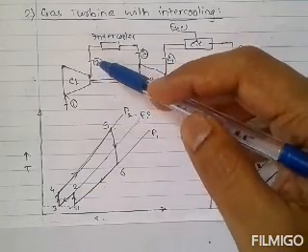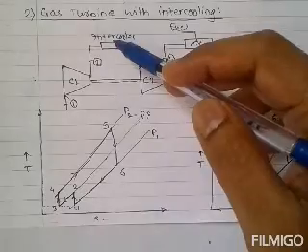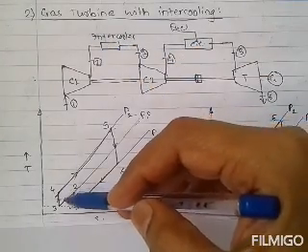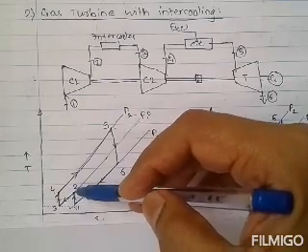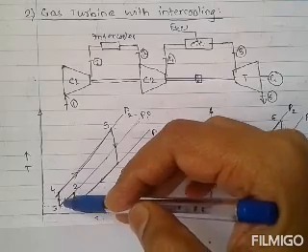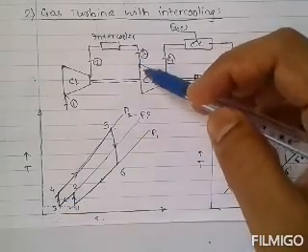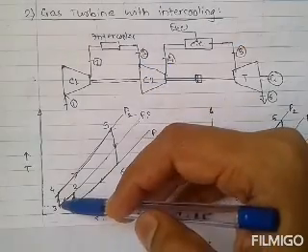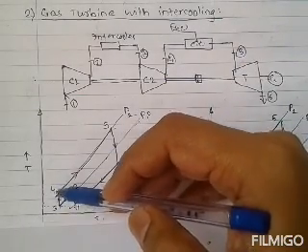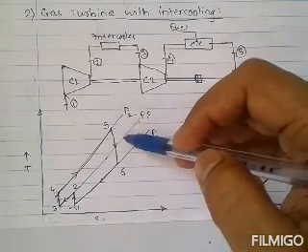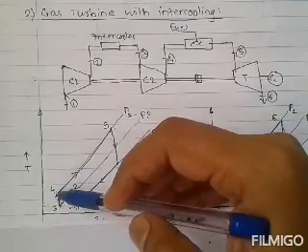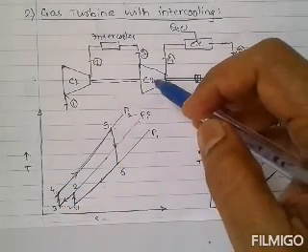After isentropic compression, that air passes through the intercooler where the air is cooled. So cooling takes place from 2 to 3, which is a constant pressure cooling process. After cooling, it passes through the second compressor where the pressure increases from Pi to P2. So 3 to 4 is an isentropic compression process, during which pressure increases from intermediate pressure Pi to higher pressure P2, in the second compressor.